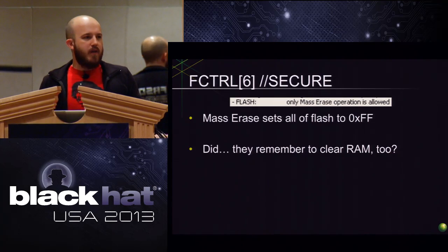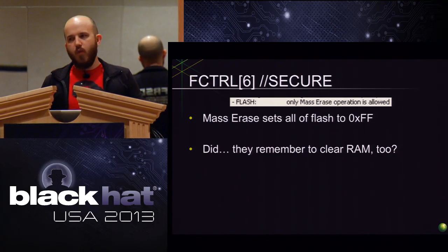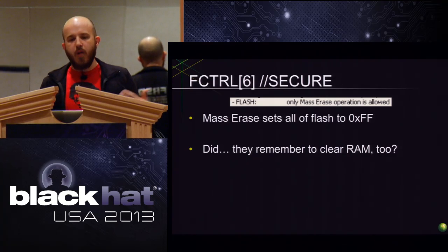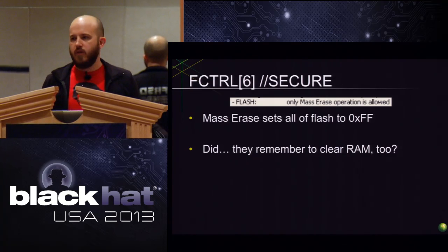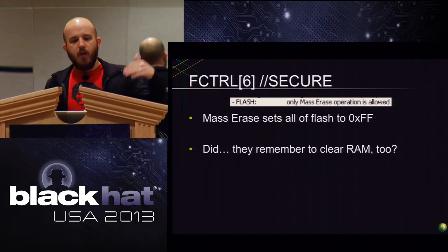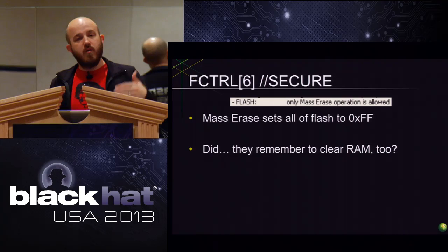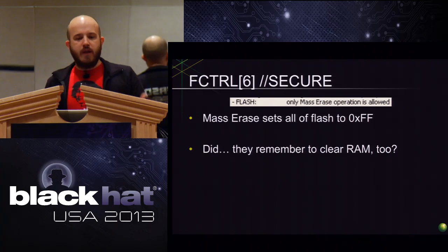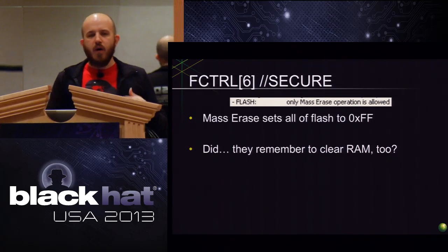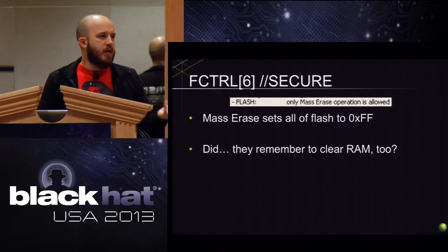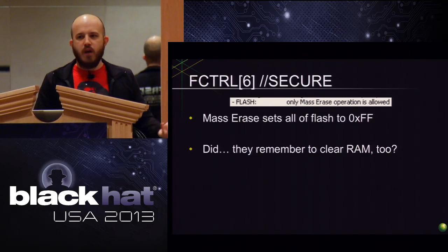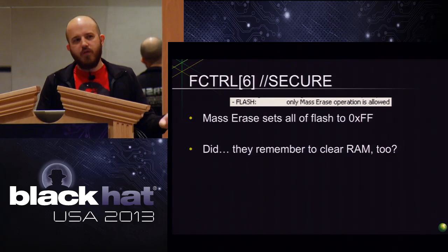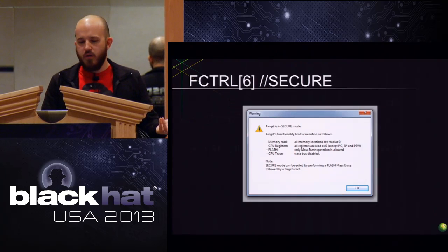So how do you get back into that device, right? They didn't want to just have that be a bricked scenario. So the common way these guys will do it, and MSP430 does it the same way, and others, it'll let you, without being able to light up the full debugging interface, perform a mass erase. So what does that do, right? It resets all the flash to FF, but there's an important consideration here. Did they also think to clear all the other locations? Because that's not the only location where something sensitive is stored.